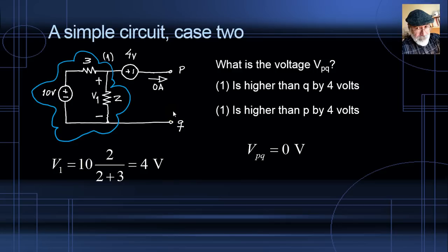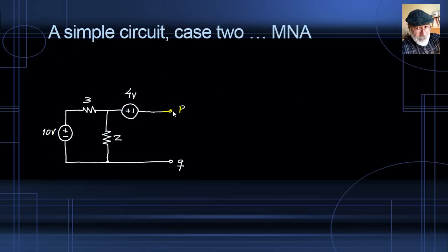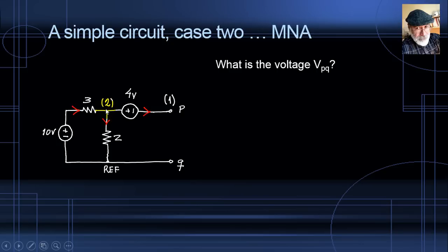What if in the exam you freeze, you forget many things and details? In that case, just use MNA. Reference node, right? Here, identify nodes 1 and 2, select the branch currents, and write your equations. Well, you say any KVL? No, but there is one evil branch now between nodes 1 and 2 and an evil current. It is one that we need to solve for.